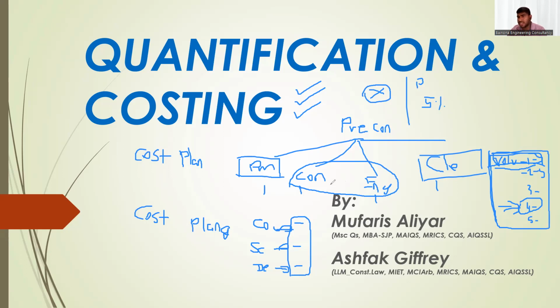And also, once the tender is done, the engineer QS or the consultant QS prepares a tender evaluation report, and the post tender negotiation, all this process is done along with the client and PMC QS with the consultant. So client QS, in summary, you can say that whatever the consultant QS has prepared is reviewed and approved by the client or PMC QS.